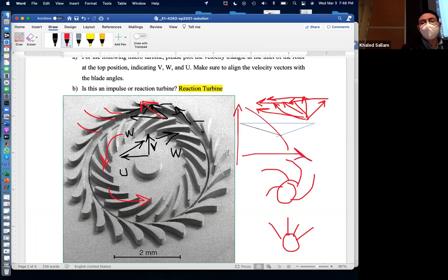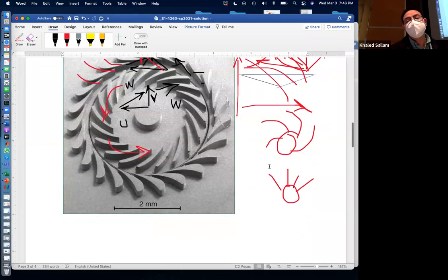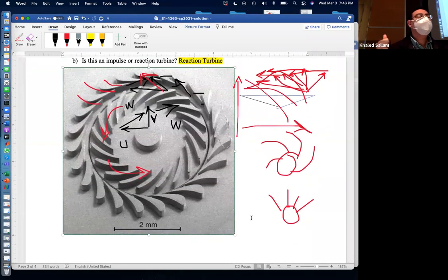So amazingly, that curve would flatten out, or even have a little bit of a hump like this, depending on whether you are radial or bent backward or forward. So the characteristic of the HQ curve depends on the geometry of the rotor, and some would be more advantageous than others. Okay? So what's important here is, remember that U plus W equals V. And remember that the blade geometry determines the velocity leaving, right? And remember that those turbomachines have to give V theta if they are a compressor. The rotor gives V theta and consumes V theta if it is a turbine.